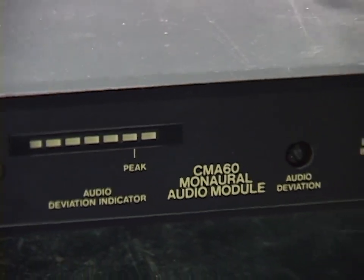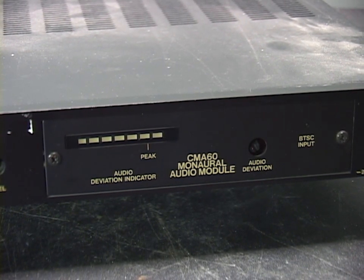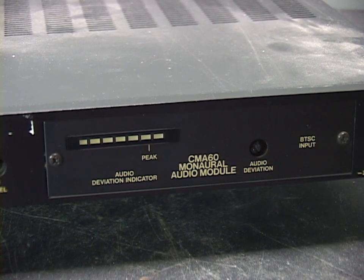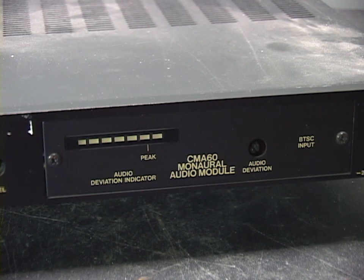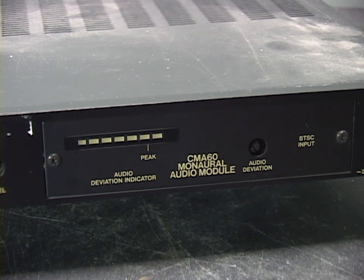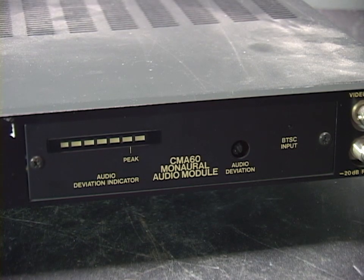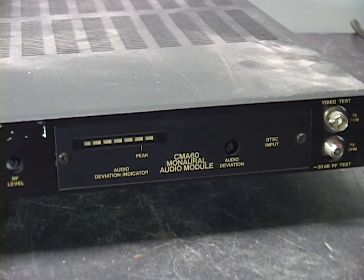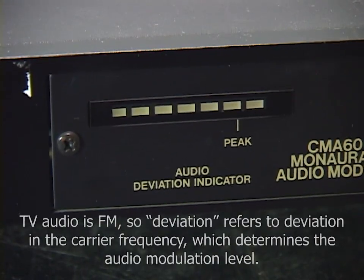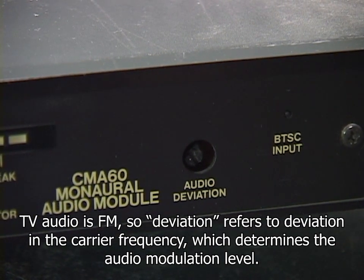Now, with these Standard Communications modulators, you had a choice of audio modules. The base was a mono audio module, which is what this has. There was also an MTS stereo module. That would be darn cool if this had that, but oh well. And then there was a module that gave you MTS stereo with secondary audio program. But on the audio module, we have a VU meter, or as it calls it, an audio deviation indicator. And then over here we have a trimmer labeled audio deviation.